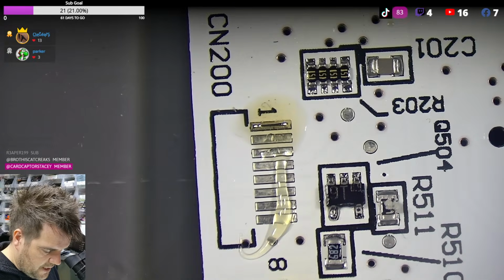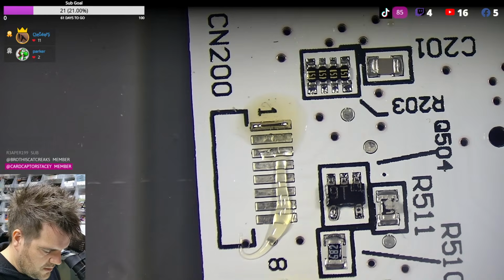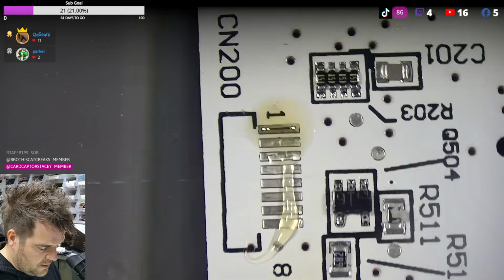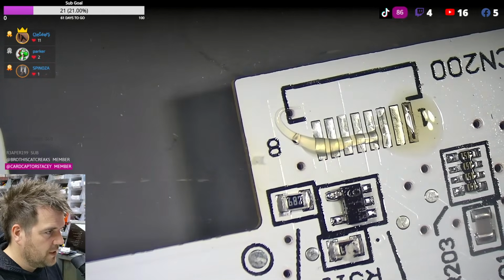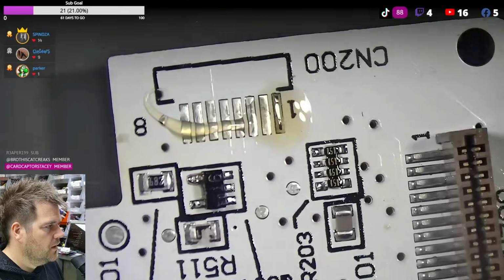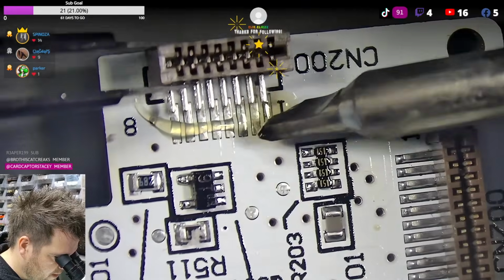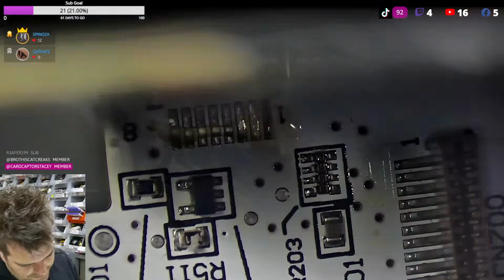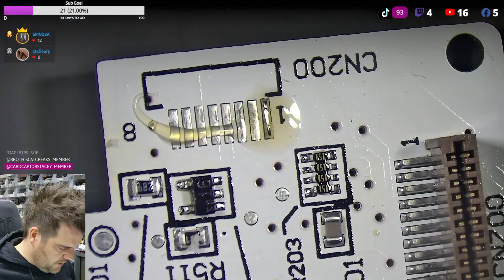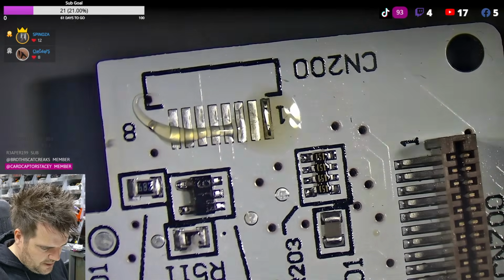And now I'm going to get the connector. It's a little bit awkward. I could do with some different bent tweezers, because I kind of want to, tell you what, I might have to turn this around this way. Yeah, just because I can't hold the connector in the tweezers. And what I'm going to do then is come down with the tweezers, warm up this pad and slide the connector in, but you don't want to slide it in and melt it on. Oh no, my little fan's run out already. That was a good fan. Plug him into charge.